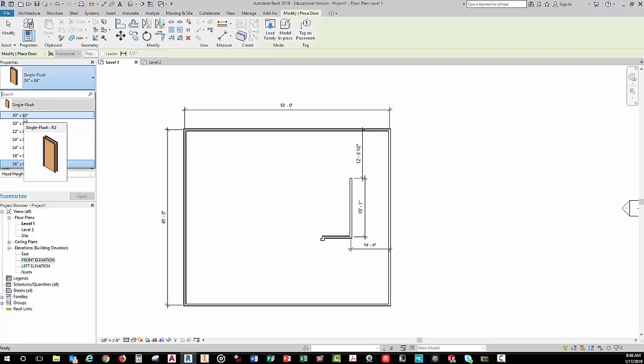Well, 6 foot 8 is your residential height, and 7 foot, or 84 inches, is your commercial height for doors. And of course your windows are located at that same height depending on which one you're doing. Or at least that's the typical head height for it. Your header is at the same height that you put over your door or window.